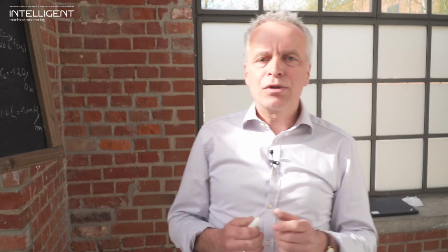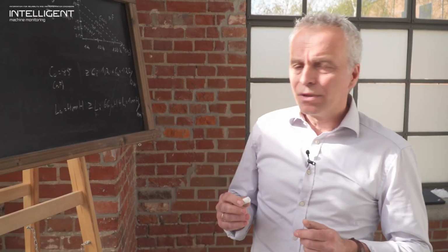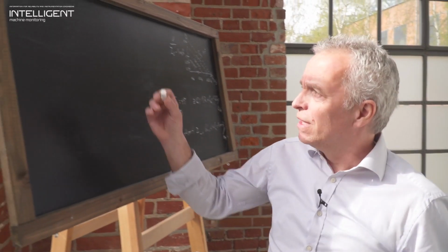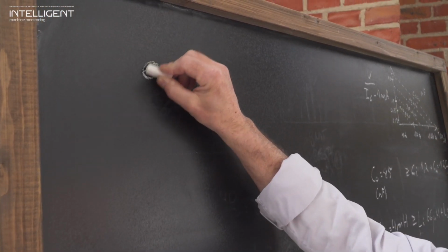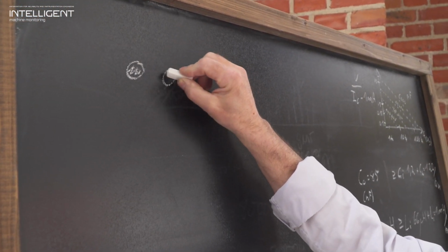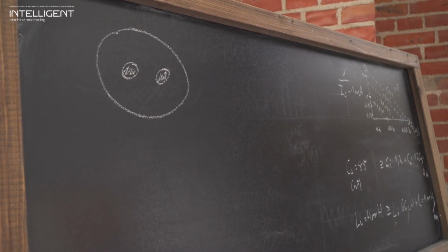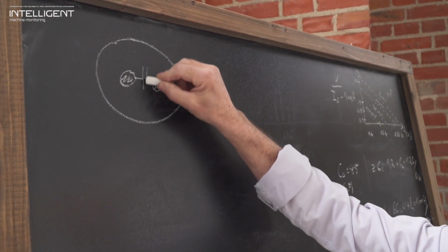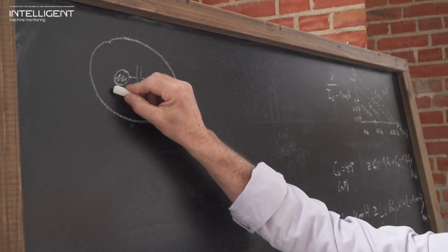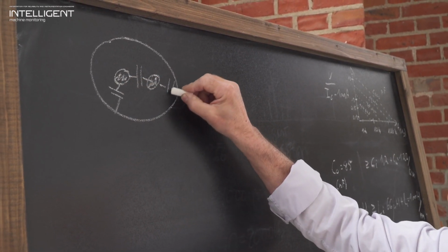So why do we talk about the maximum cable length at all? For this, we have to look a little bit into the physics of a cable. If we take a signal or a cable pair, for example, in a multi-core cable, where we have here the cores and here we have got the shield, each cable has a capacitance between the individual cores and between the cores and the screen.